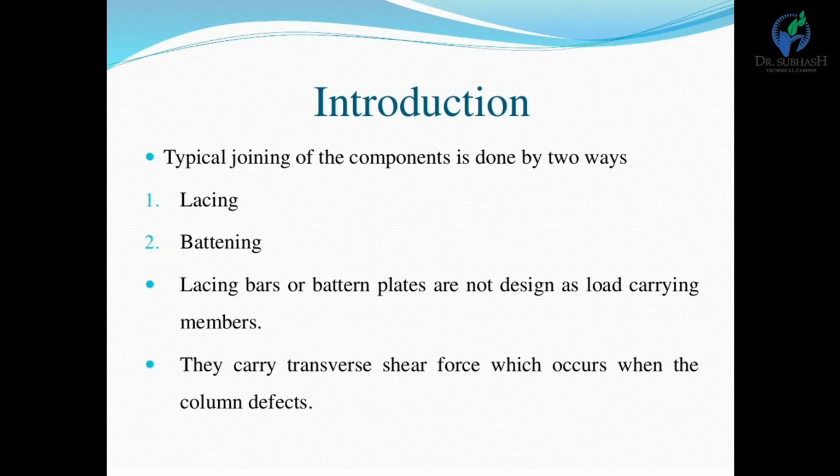Before we start lacing, we should know the function of lacing and battening plates. The function of lacing bars or batten plates is to hold the main components of the built-up section in their respective positions and to resist the stresses in them. They are not designed as load carrying members, but they can be designed to resist transverse shear force that occurs in the column.